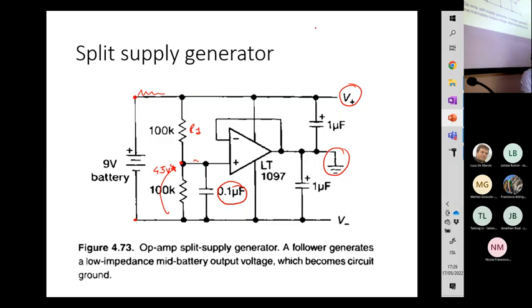And then, well, you cannot connect this node directly to the circuit that you want to drive, because if this voltage divider is attached to a circuit with a given input resistance, so this is R1 and R1, well, the partitioning between R1 and R1 is different with respect to the voltage division between R1 and R1 parallel Rin.